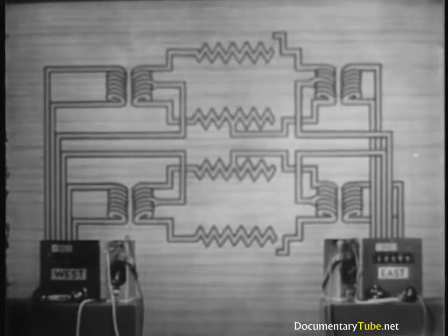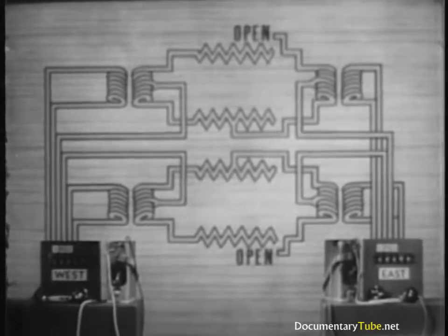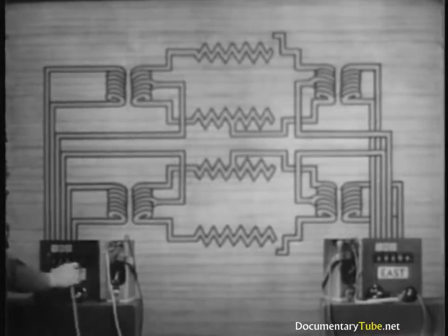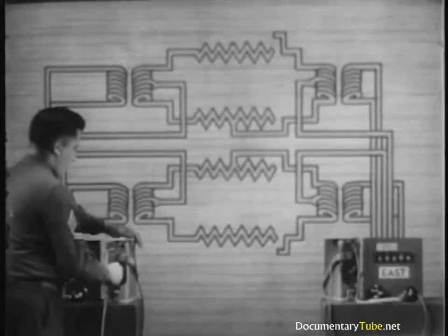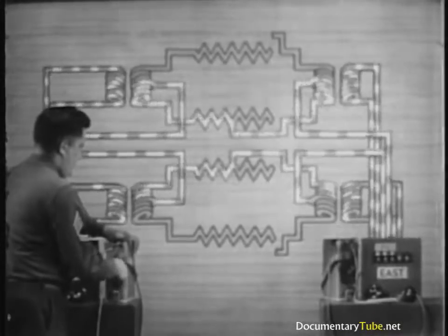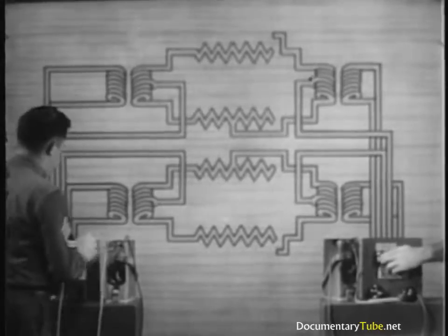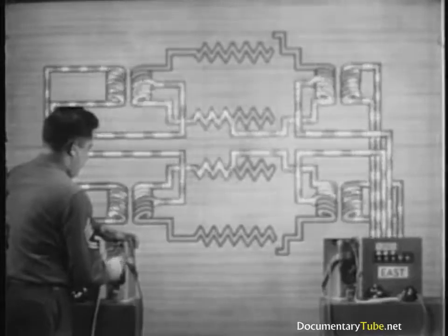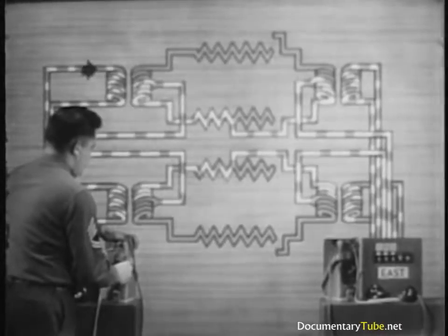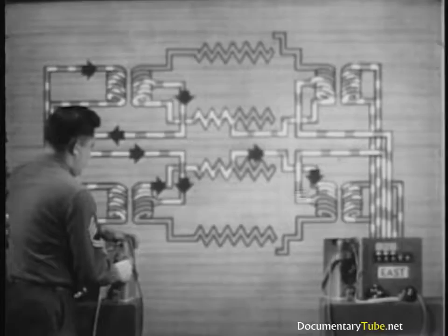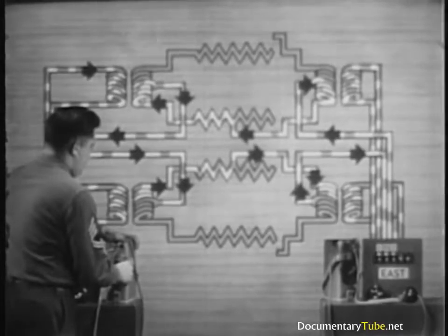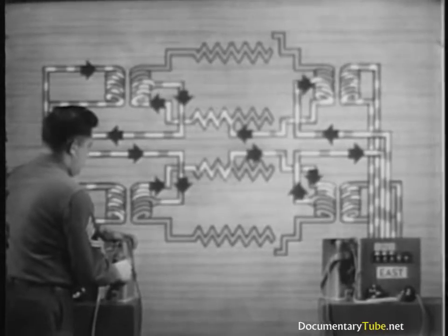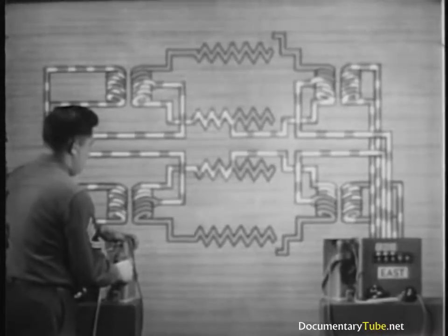What happens if both side circuits are open? This one's tricky, for now, both sets of repeating coils are unbalanced. Ringing on either side circuit, we find that current flows through every possible drop in the phantom group. The jack we ring on is, in effect, connected in series to the other 5 drops. Either side circuit then interferes with both the phantom and the other side circuit.